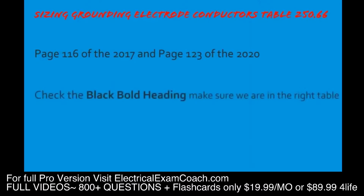Let's learn about sizing grounding electrode conductors. Everyone head to table 250.66. It's on page 116 of the 2017 and on page 123 of the 2020. Pause the video now if you need to. So the first thing we do there is check the black bold heading and make sure that we're at the right table. I cannot stress to you enough, the next 3 tables that we're getting ready to learn almost look identical. And if you don't read the black bold heading when you get to the table, you can be off in a heartbeat.